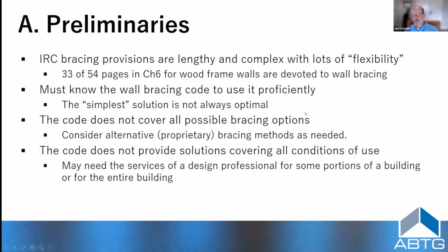And one of the fallacies is that there's a simple solution in there. There's no silver bullet, in the sense that no matter what product you use, no matter how strong it is, you have to use it in the right amount. You have to install it the way that it was intended to be installed. The bracing panels need to be of the correct width or configuration to be able to actually provide the resistance that's needed.